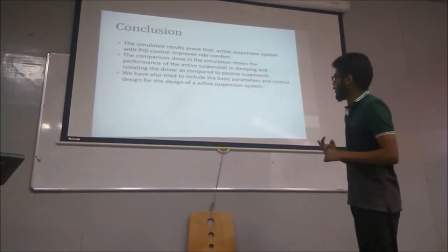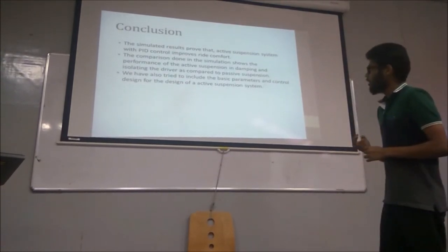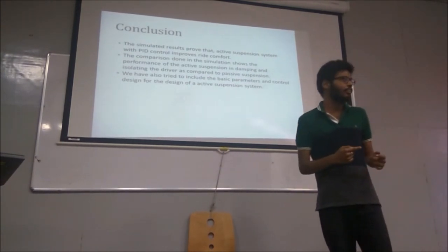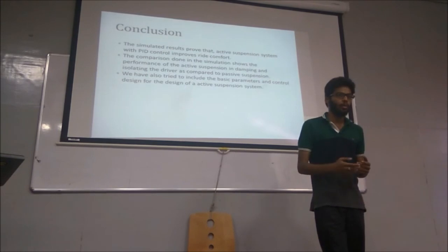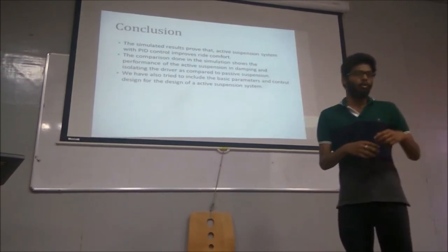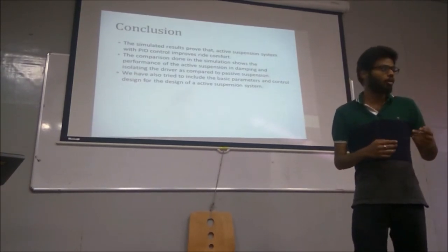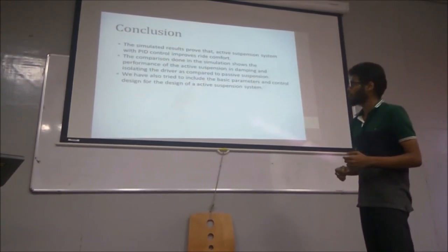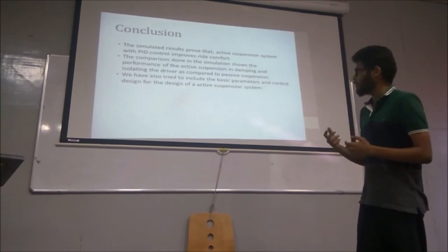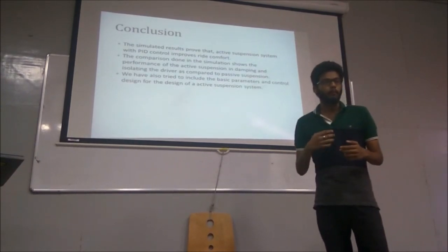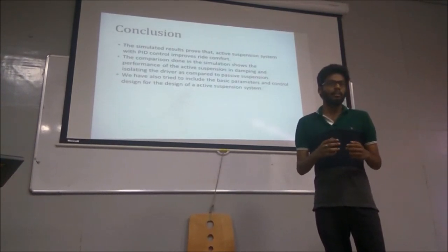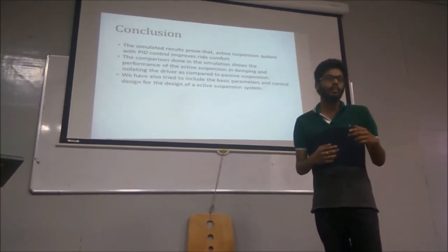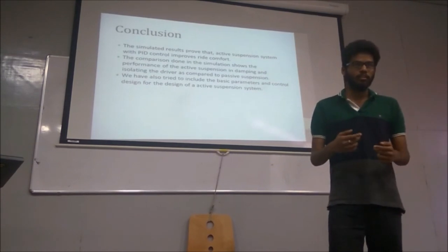suspension system. The comparison shows that the active suspension system very efficiently isolates the driver and the passengers from the various shocks of the road, irrespective of whether it is a pothole, a bumpy road, or any random road for any given stretch of time. We have tried to include the various parameters for the design. When we talked about the PID controller and the hydraulic system, we talked about the various components as well as the various parameters which control these components.